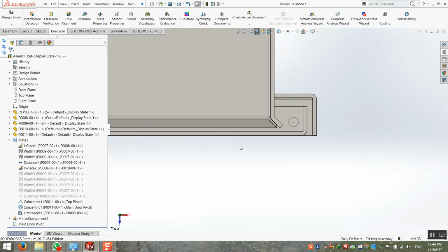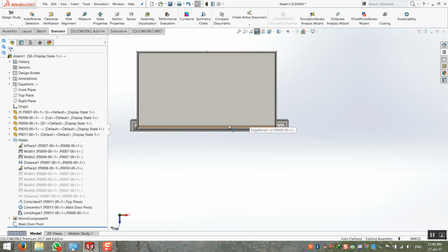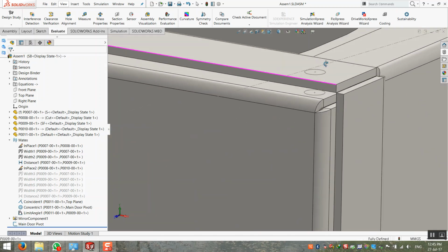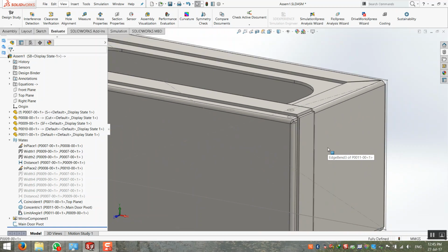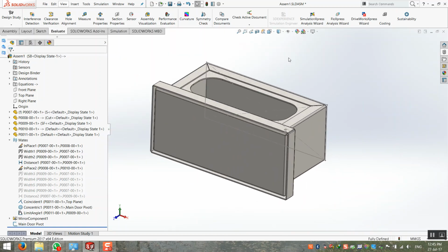Now the gasket will be, I think, 5 millimeters. And when this gasket is pressed, it will compress to 2 millimeters, so it will be waterproofed. All right, so you are finished. This doesn't have any problem. You can just cut, in this very simple way. You can cut it like that.